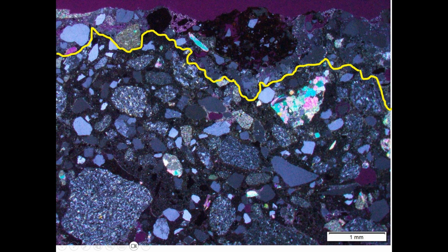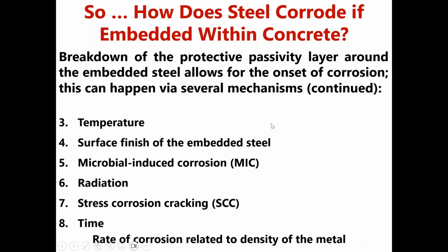This is a good example of why a lot of these projects can benefit from petrographic analysis and also be augmented by water soluble chloride analysis, at different intervals at depth, to really get a handle on how deep the concrete may have been affected by the chlorides.